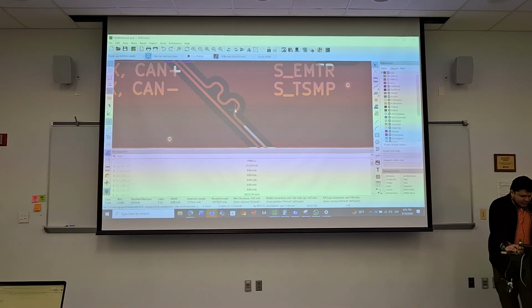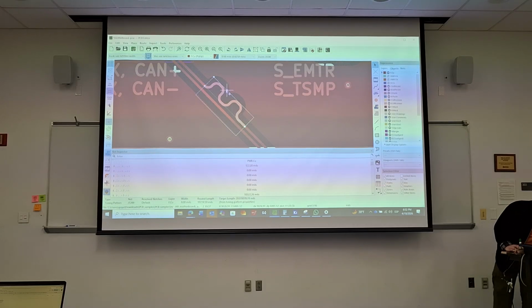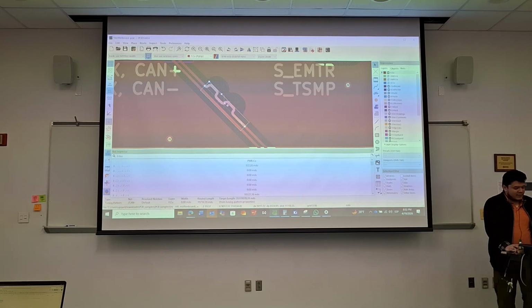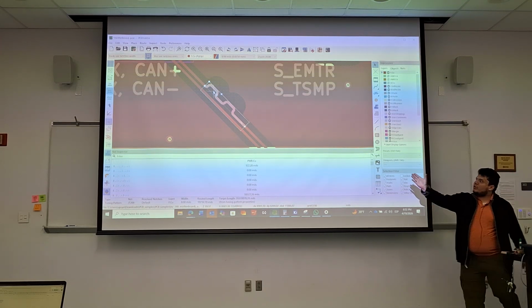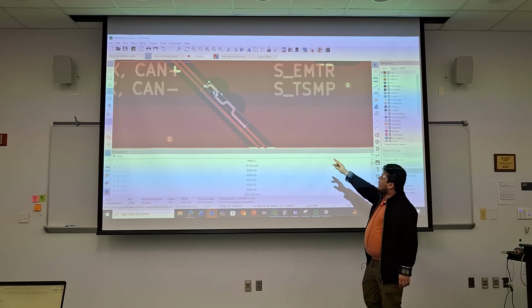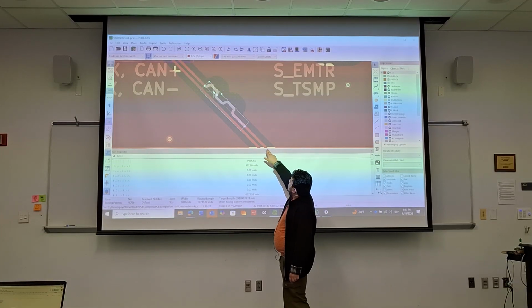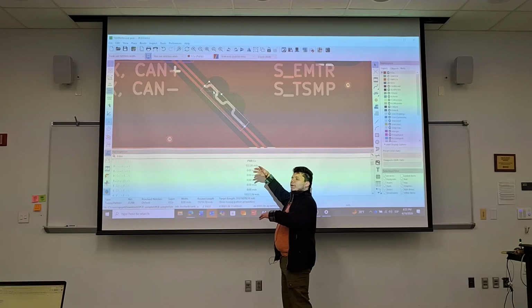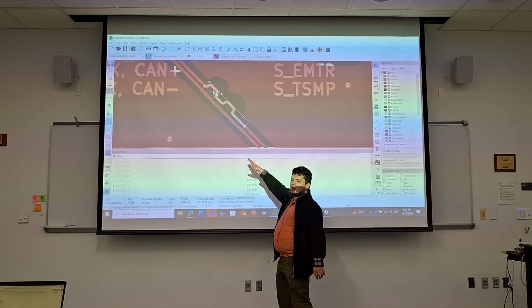Yeah, I don't know what they were doing here. And normally, I don't know if there's a way to change it here, but there we go. You don't want to tune too high. Really, this should be tuned at most one spacing out. So if our spacing is pretty close, we want the skew to also be that, because otherwise you lose coupling, right? You want to keep this coupled the whole time.